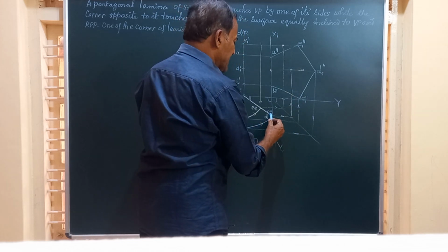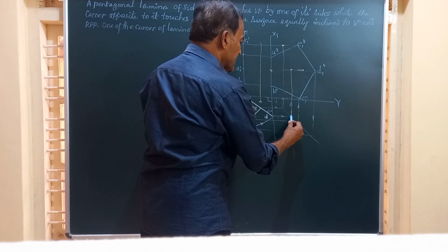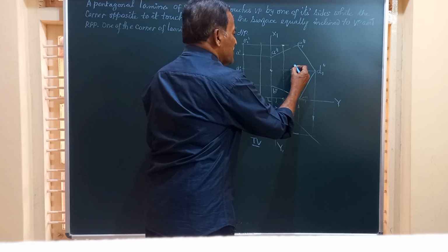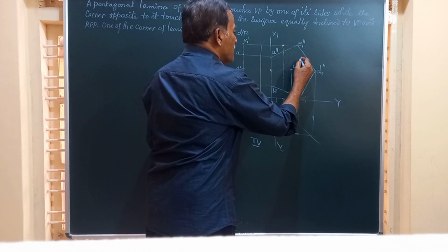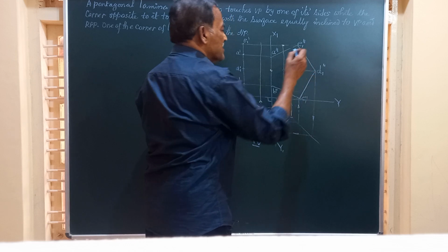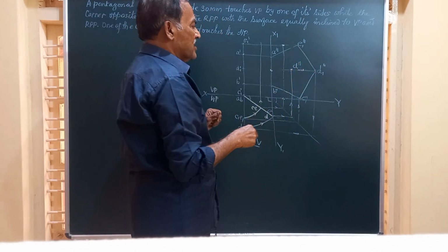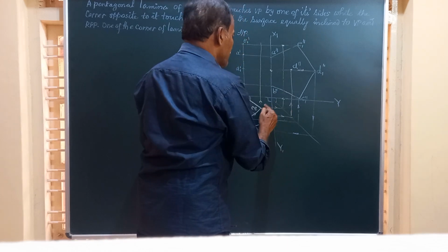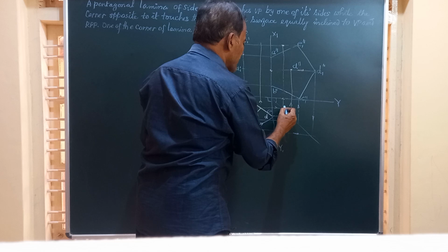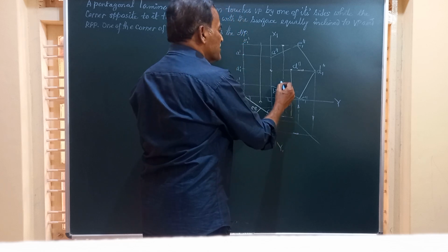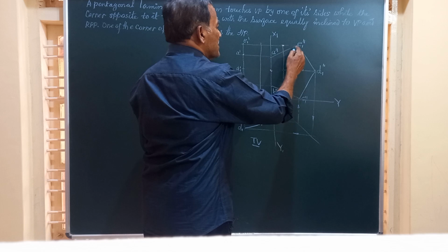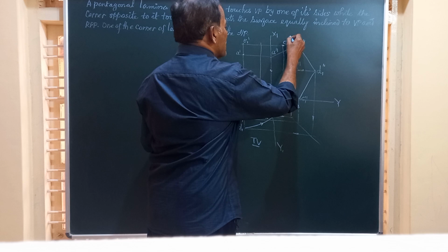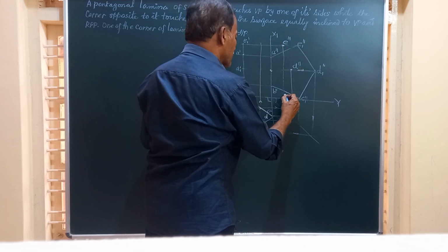So if you start with point D, write a horizontal line through D, take it upwards till it touches the horizontal line drawn here, and this point will give you very obviously D double dash, the final end view of the corner D. Next friends, you will take C and E, write a horizontal line from here, a vertical line from this, and the point on this locus of E and C, you will get the point E double dash, and this is going to be C double dash.